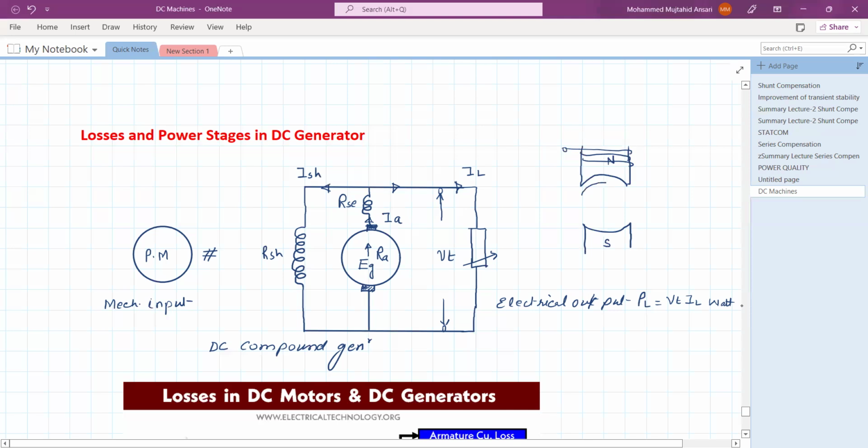When the armature core, which is made up of magnetic material, is moving under the presence of magnetic flux, this is a metallic part, that is, a conducting part. So whenever the conductor cuts the magnetic flux, it induces EMF. If you look at this armature structure as a three-dimensional view, it induces some EMF, but it does not find any external circuit, as with the armature conductors. There are different armature conductors over the periphery, or slots. So this structure does not have any external circuit.